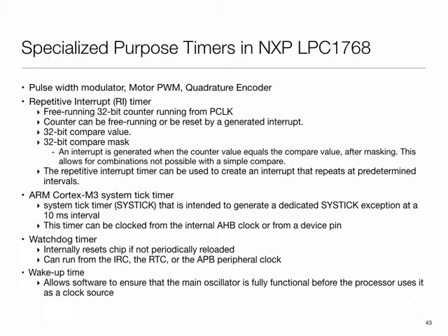If you look at microcontroller chips, you'll find that the actual processor core is a very tiny thing, maybe 10, 15, 20,000 gates. It's the peripherals that occupy the bulk of the area, because by providing these counters and timers, you are doing a couple of things. Number one, you are enormously simplifying the software.